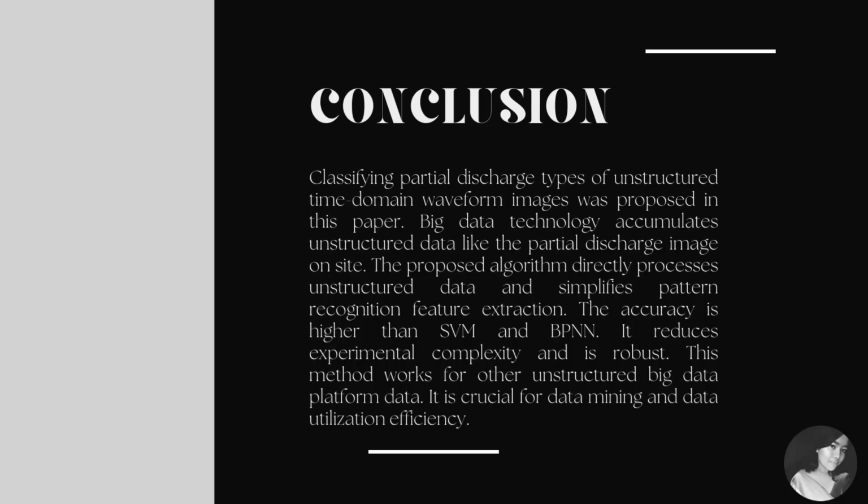Classifying the partial discharge type of unstructured time domain waveform images was proposed in this paper. Big data technology accumulates unstructured data like partial discharge images on site. The proposed algorithm directly processes unstructured data and simplifies pattern recognition feature extraction. The accuracy is higher than SVM and BPNN. It reduces experimental complexity and is robust.